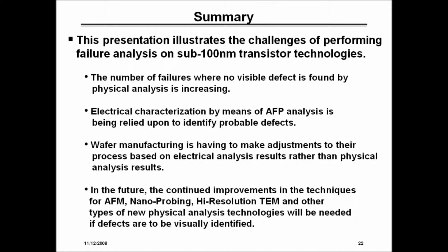Or if you've got multiple inputs at a higher layer of metallization, you can probe at that metallization and sweep it and see if any of the inputs going into that circuit is leaky, or on the outputs, if any of the drains that are connected together have a problem. You can narrow it down, but it becomes more laborious because you have to start at a higher level and then work your way down, measuring at different metallization layers. Probably about half of our submissions now we have to probe at metallization, on the copper metallization.